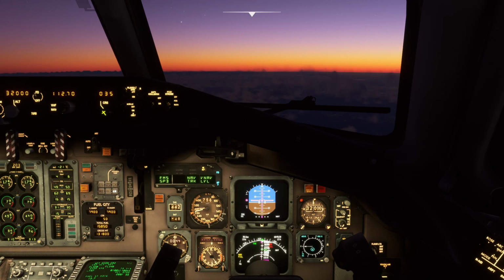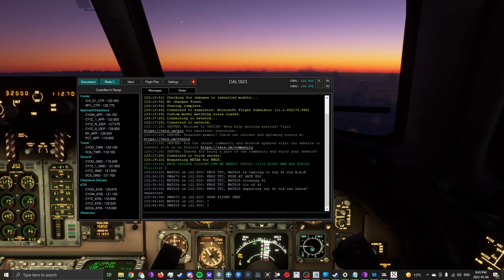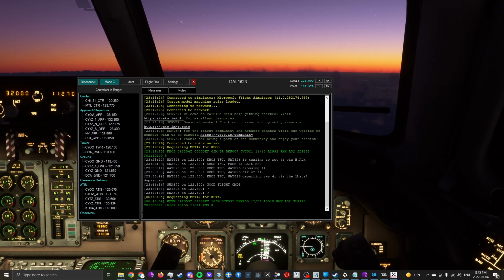There's no ATIS online for Detroit Metro, so we're going to grab the weather from vPilot. The METAR is showing wind 020 at 6 knots, 10 statute miles, scattered 3,500, broken 2,500, temperature 15, altimeter 3018, remarks, stuff. Not icing conditions, so that's good.